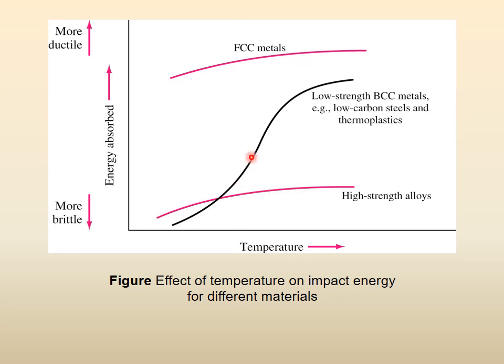But if the temperature goes low, below a certain threshold, then this very high toughness goes to very low. So this is the ductile to brittle transition type of materials. And there is a certain temperature range. For many metals, it is close to the freezing temperature, that when it goes to freezing or below freezing, then this material at room temperature was a very nice ductile material with good toughness. Now it has suddenly become a brittle material, right? So these materials are all one kind. These are good toughness. These are low toughness. These are ductile. These are brittle.